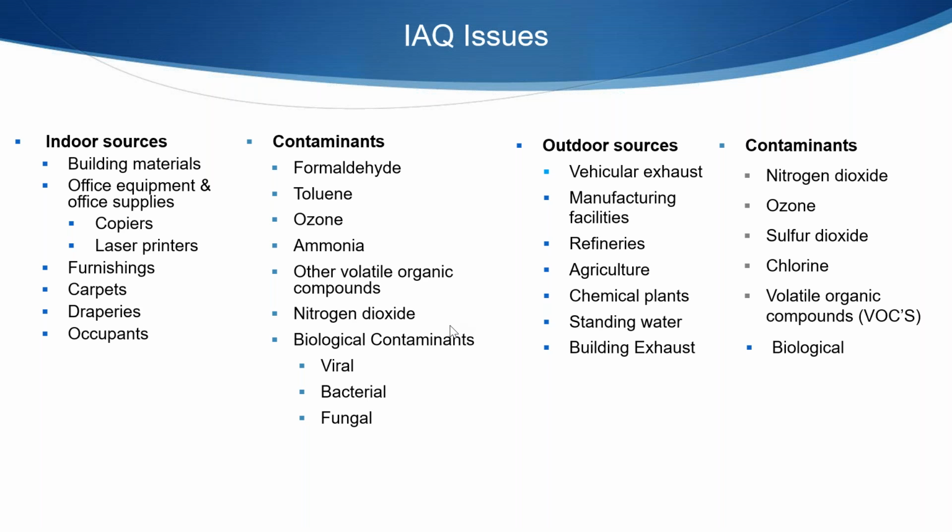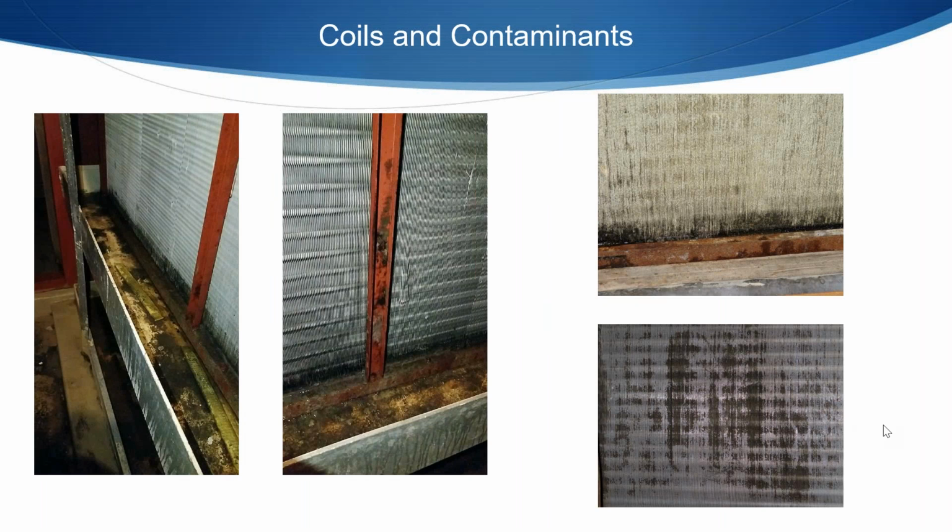I also had a customer in Los Angeles whose building, when designed, had plenty of space between the building exhaust and the intake. The intake was sufficiently distanced from the ground. Everything was fine. And then recently a two-story tent city has popped up nearby, and they have contaminants coming in from the new residents living right at the side of the building. That was one I was not expecting. I was like, you've got outdoor air coming in, I'm not sure you're going to need this in this case, and that was the conversation that was had. So, not to take for granted those assumptions that we sometimes make, there might be applications out there where it's a perfectly appropriate fit to try to treat the airstream.